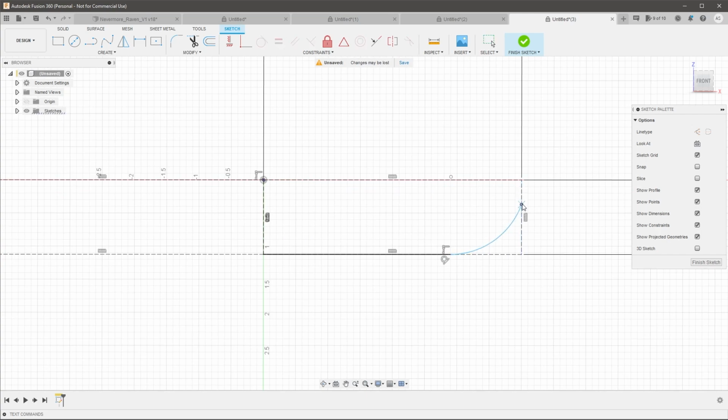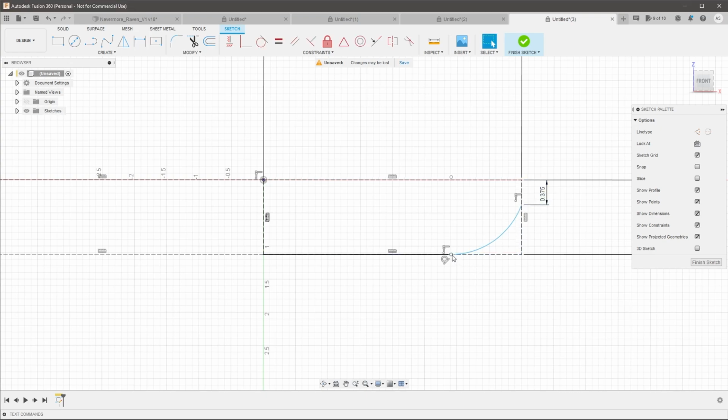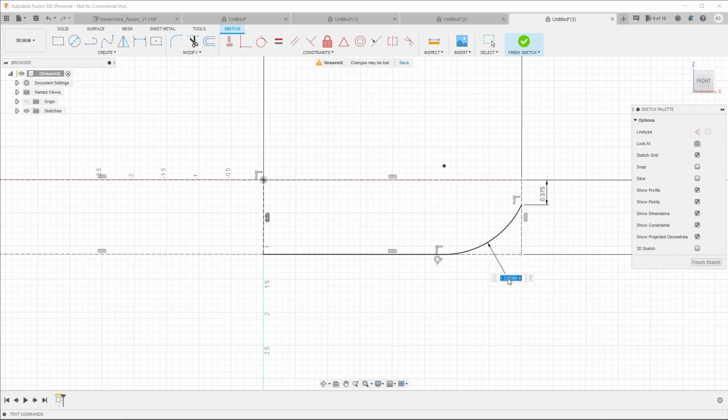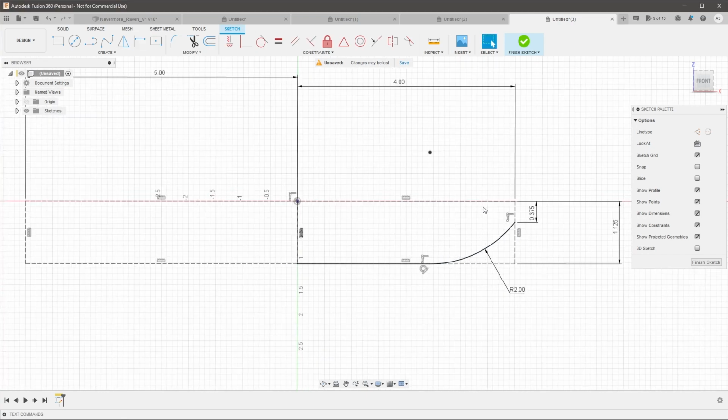And then let's go ahead and define a point. How far down? We're going to be doing a drop point knife. So how far down do we want that drop to be? So I'm going to say from here to here, we're going to do 0.375 inches. And now the only thing it really doesn't know is what is the diameter or radius of this arc. So I'm going to give this a 2-inch radius. So that part, the edge part of my knife is already done.